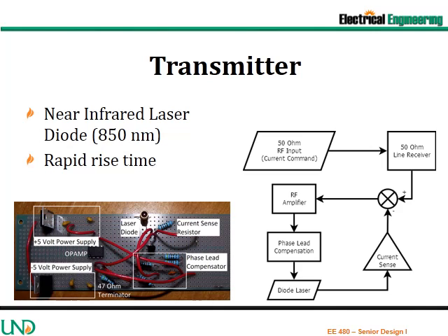This module was the first to be soldered to a perf board. On the breadboard, alligator clips and leads were required to position the laser diode to be in line of sight of the receiver. This resulted in a 9 nanosecond lag for the current signal. This, coupled with the capacitive load of the laser diode, resulted in oscillations which showed up as noise on the receiver. When the laser diode was placed on the breadboard, the ringing was excessive due to the high capacitance of the breadboard. As a result, prototyping was required to be moved to a perf board.